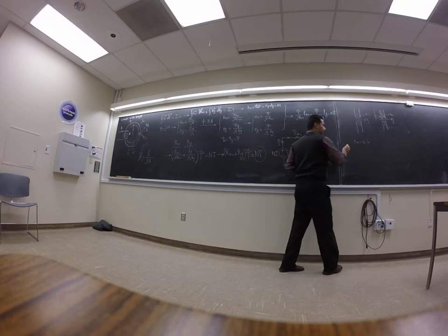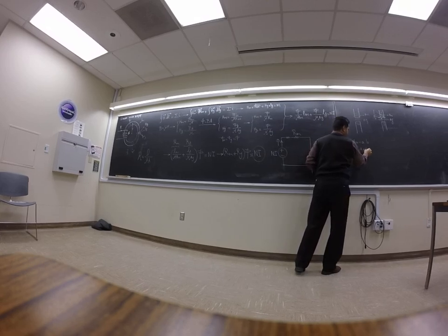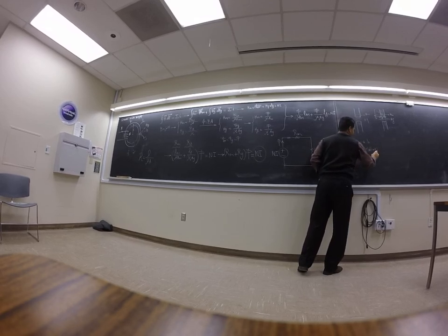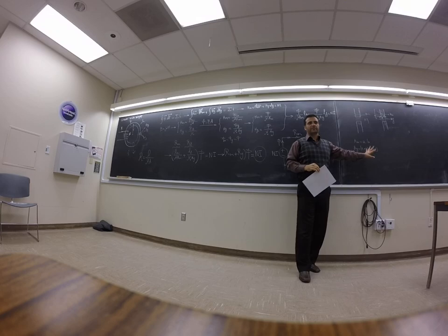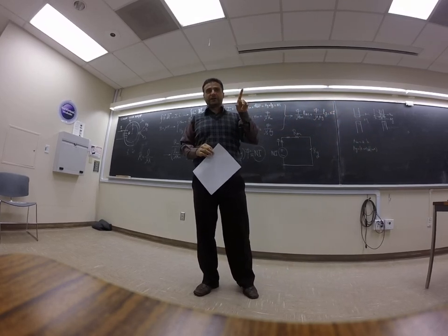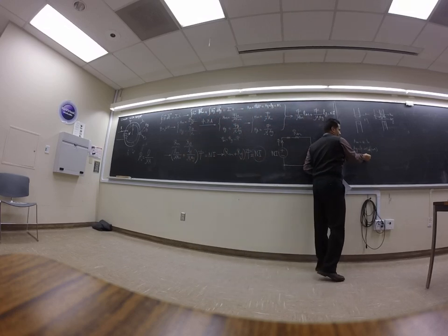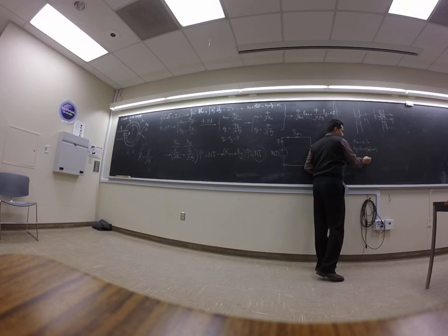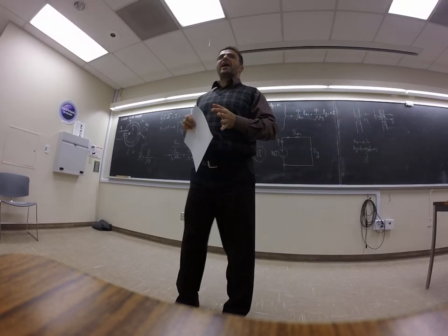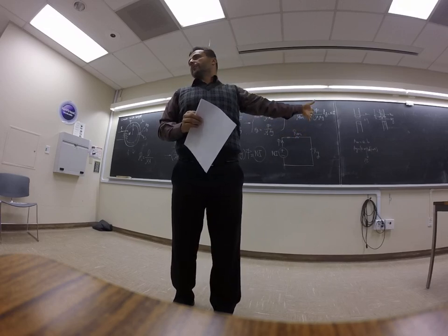AM is A times B. But AG, they say, for example, A plus X times B plus X. X is a fringing effect, 5%, 10%, something like that, if you want to consider the fringing effect. You don't know how much X is, but either the problem tells you, hey, consider 5% fringing, or I don't know, 10%, or if we don't say anything, just assume it's ideal. AG and AM are the same.